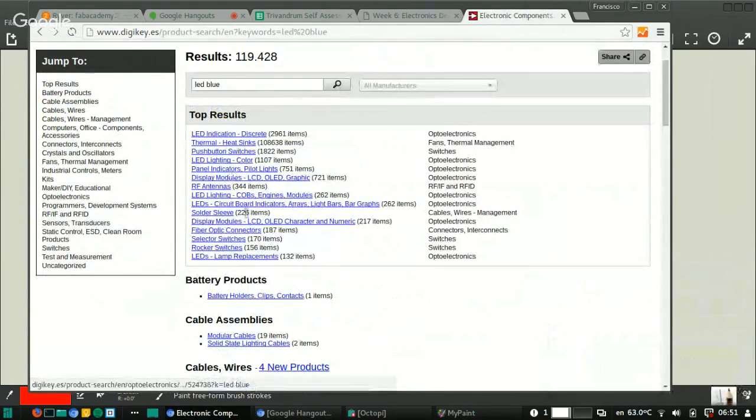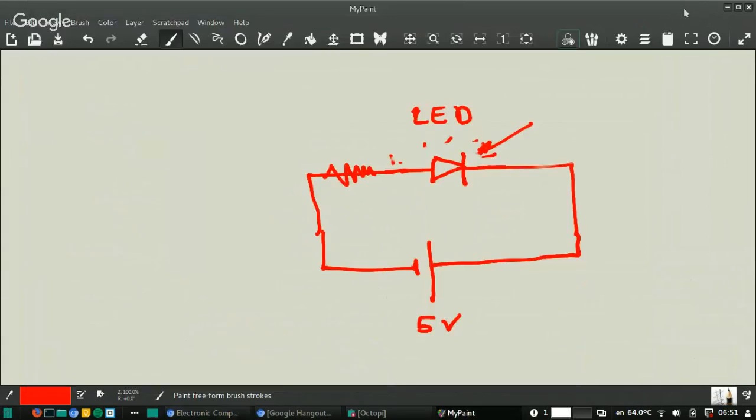And inside the datasheet, it will tell you the typical current of this maybe is 2.5 milliamperes or 5 milliamperes, and then you have to do the calculations. And what is the resistor value you should put here? So basically, you would advise that we draw out the circuit, look at the different calculations, and then attempt to insert the new elements like the push button and the LED, right?